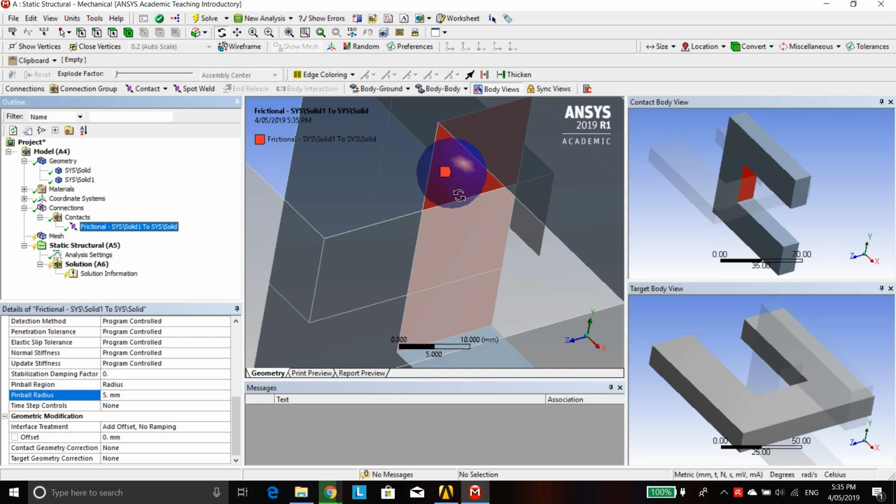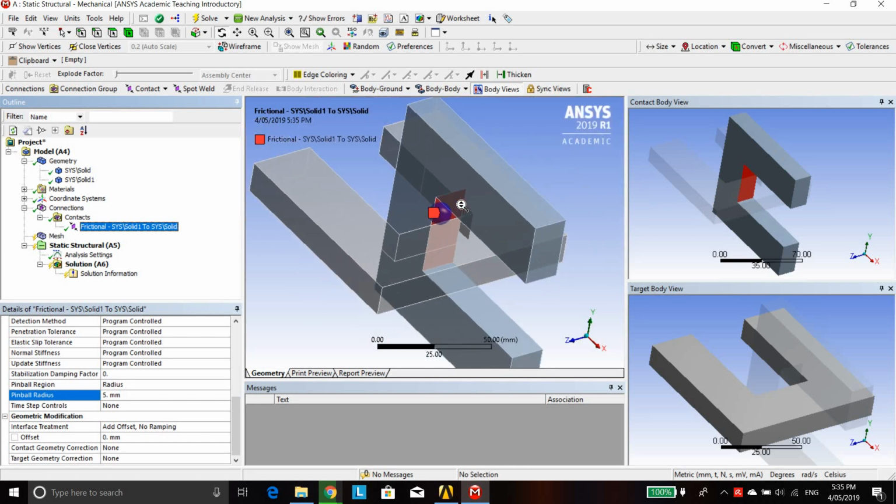So what is the application of this? When ANSYS solves the contact simulation node by node, ANSYS is going to say, okay, let's check. I'm solving force for this node at this contact. How many nodes are in contact with this node? ANSYS doesn't know the geometry, so it's just pure math. It is going to start looking for those nodes, check them based on the x, y, and z to see if they are in contact with this node.